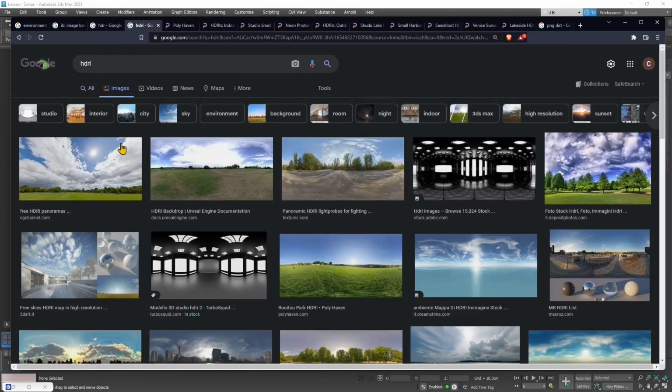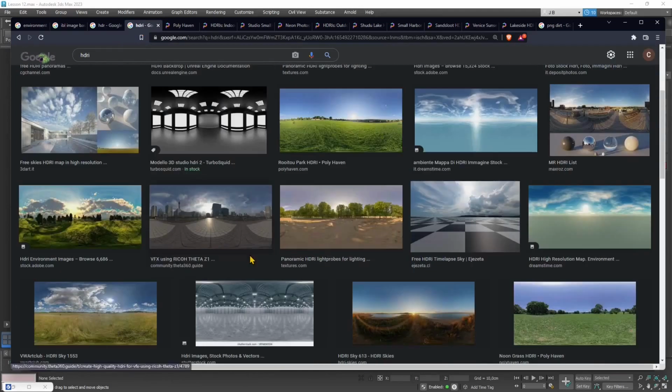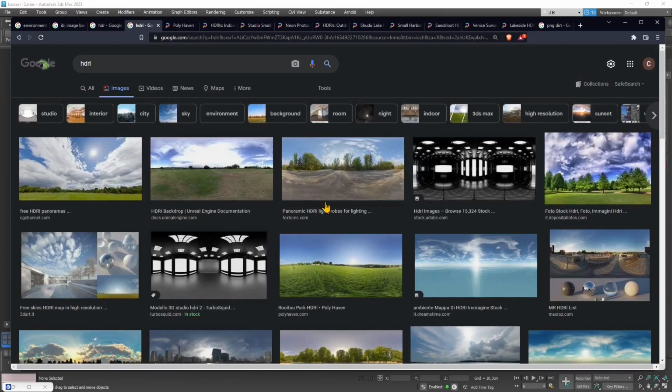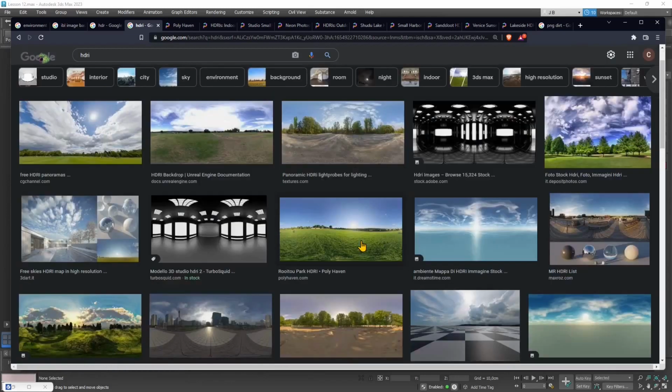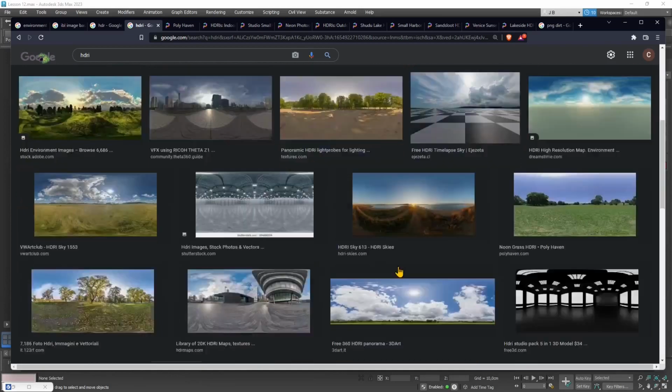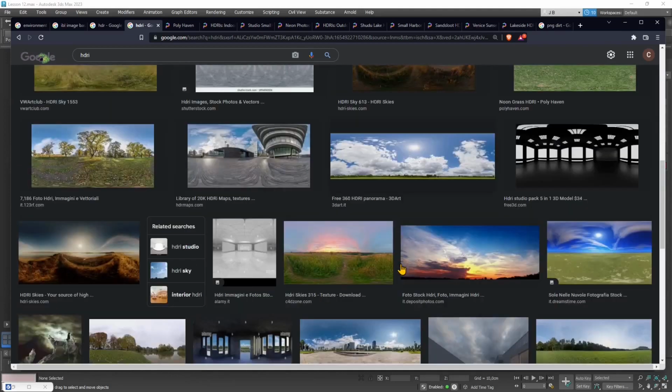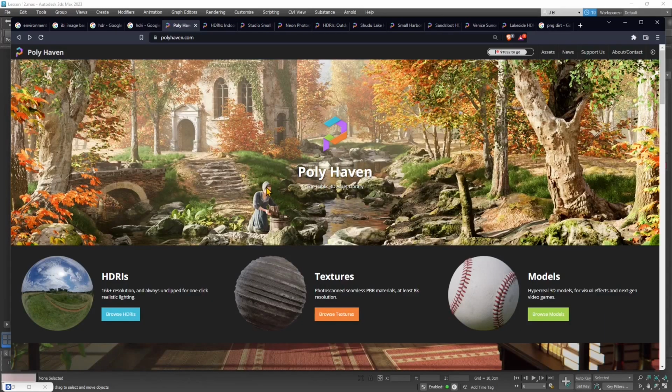And if again we search for images here, we're gonna find the same exact look of the environment texture. So the HDRI, or high dynamic range image, is actually an environmental image that is gonna be placed around our scene, kind of like a sphere surrounding everything. So it's gonna give us a context, and I can change context by changing the HDRI. I can create an interior rendering, an exterior rendering, a studio rendering, and so on.